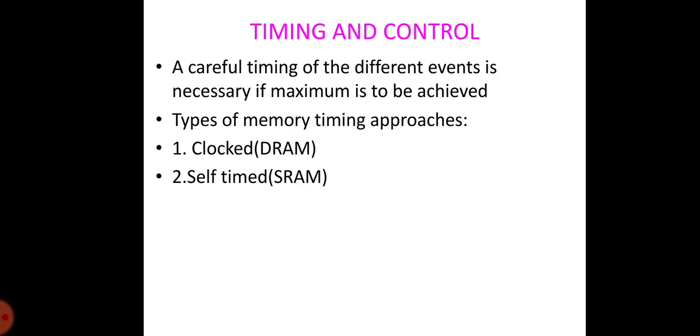This presentation will give you a picture of the memory model as a complex entity whose operation is governed by a well-defined sequence of actions such as address latching, word line decoding, bit line pre-charging and equalization, sense amplifier enabling, and output driving. To be operational, it is essential that this sequence be adhered to under all operational circumstances and over a range of device and technology parameters.